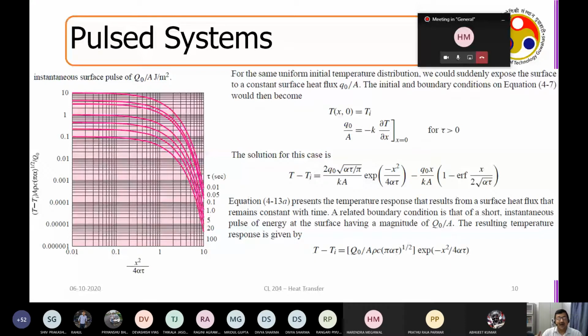So what we did, we smartly took just the conduction term to study the steady state part. We took the transient term to study the parabolic part, and in that manner, we reduced these equations to manageable forms that are required for the systems that I'm choosing. And then we assumed separation of variables and very smartly enforced the boundary conditions to get simple analytical solutions like this, which can really describe, suppose this is a slab, how the temperature is changing in terms of space and with time.